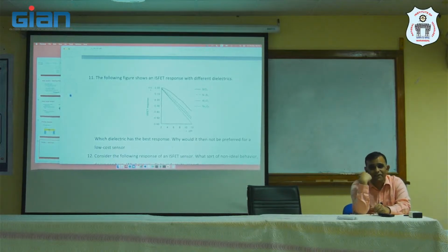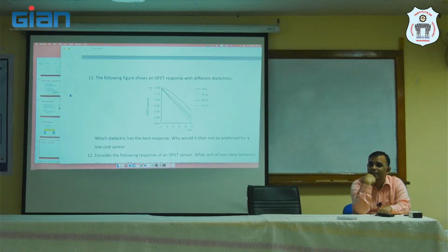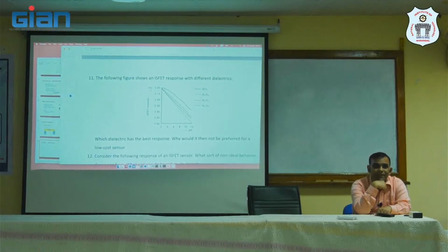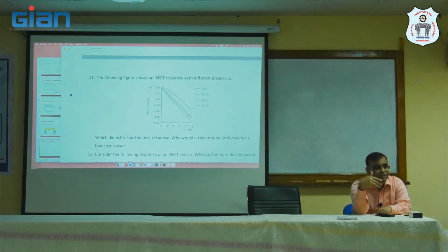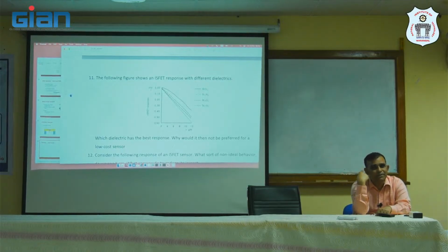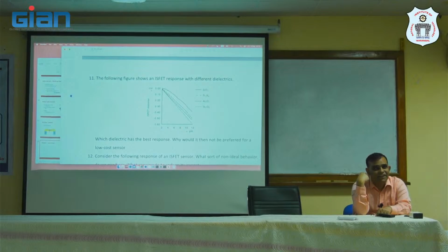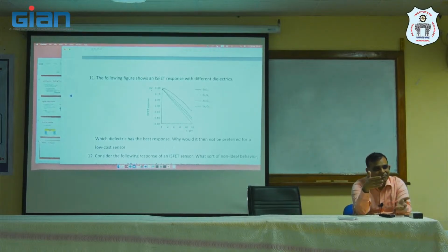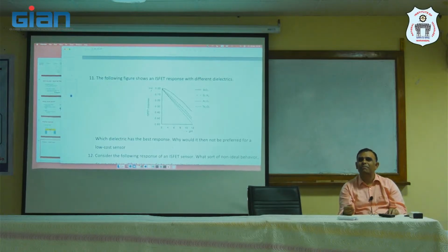The main cost is not in depositing. Things like silicon dioxide are already there on a chip, right? You don't have to do anything else for silicon dioxide deposition. Whereas in order to deposit tantalum dioxide, you need to first remove the silicon dioxide and then deposit. So you are putting 3 or 4 new layers of production. Remember we did CMOS production the other day, where each layer caused a lot of sequence steps. So each extra step cost us a lot of money.